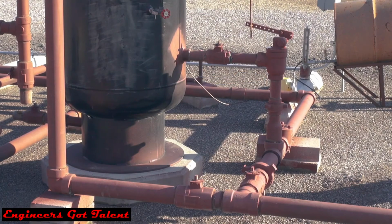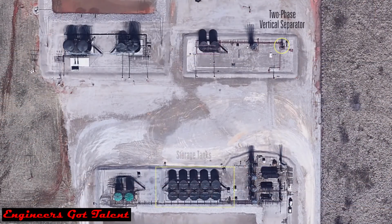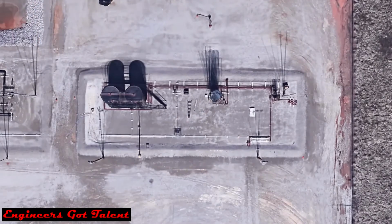The oil, the water, and any solids that might be in the liquid flow down this pipe into the dump line. And in this case, the dump line could go to a couple of places. It could go to a final destination of a storage tank, but in this case, the producer needs to further process the emulsion in order to make it sellable. This emulsion then will go down the dump line into another vessel, and that vessel is called a heater treater.